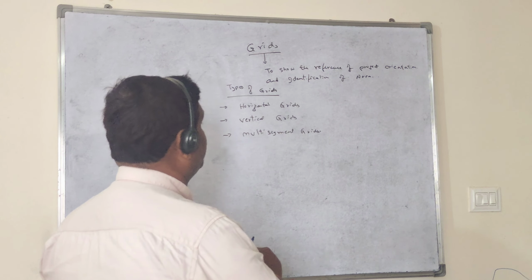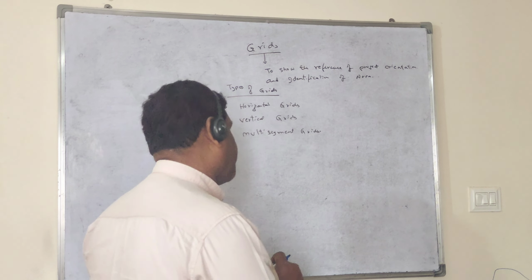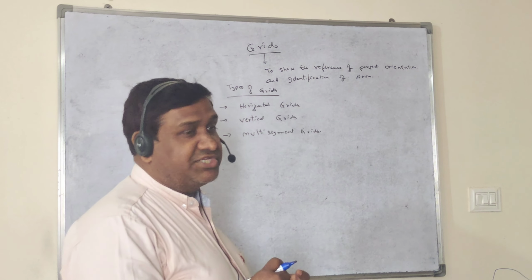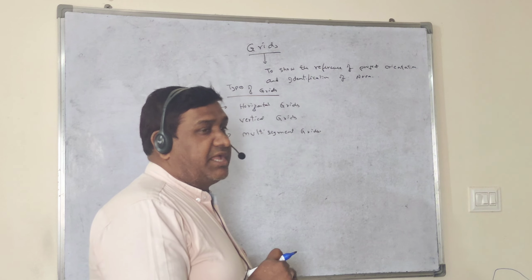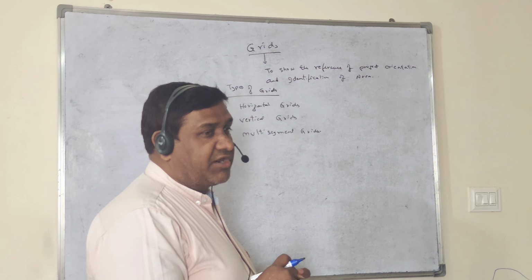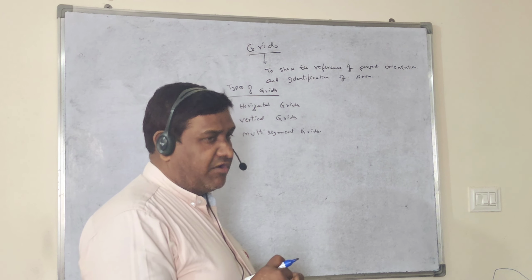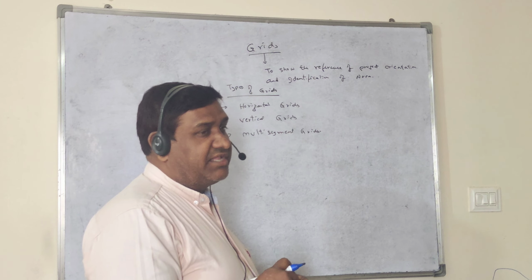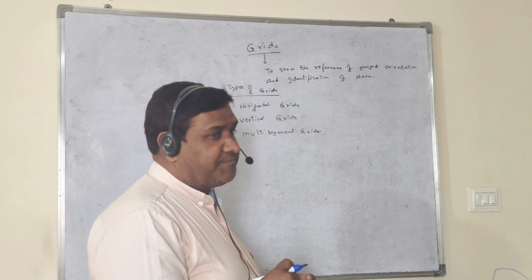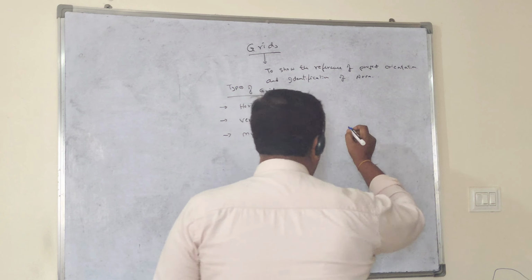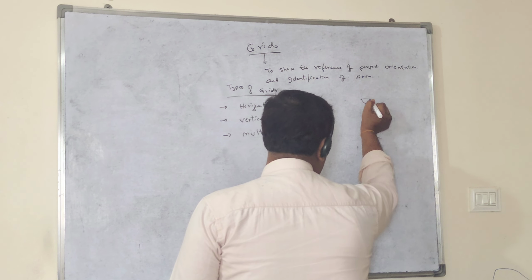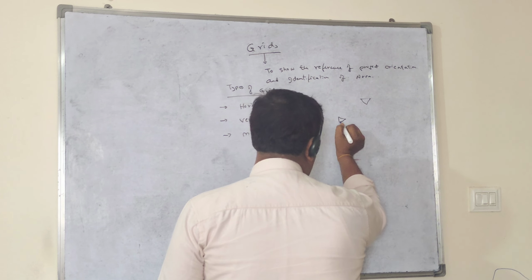So where do we have to place the grids in a project, and why is it very important? Because in a project, wherever your columns or footings or foundation will be, in the center there will be a grid. Right now, as I already told you, you have seen the elevation symbols in Revit.